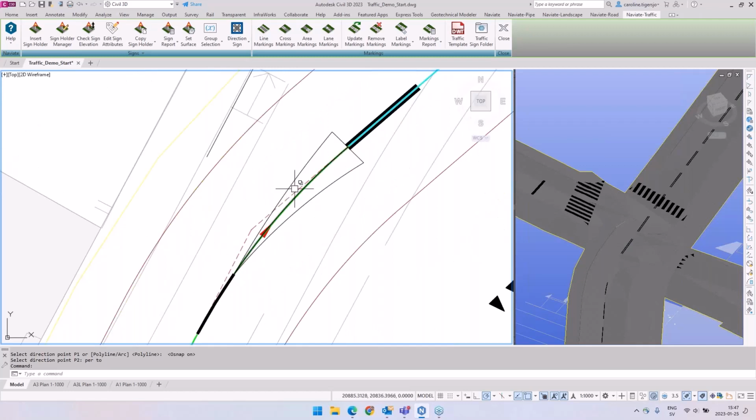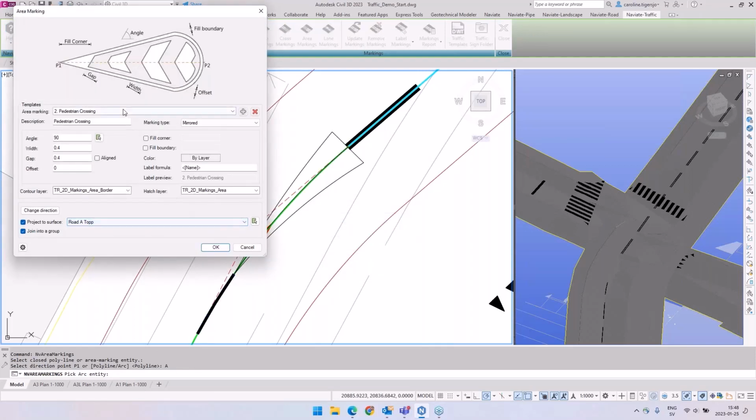So in this case, I have a ghost island prepared, and I want this to be filled in, and I want the middle line to be this arc in the middle. And that is something that has come in the later version, where I can select my closed polyline, and then I select an arc down here, and I select, let's see if I got it close enough.